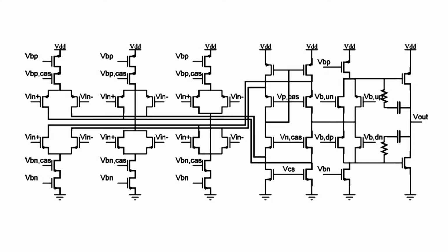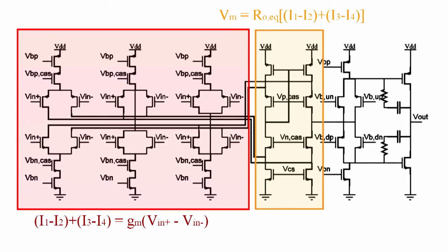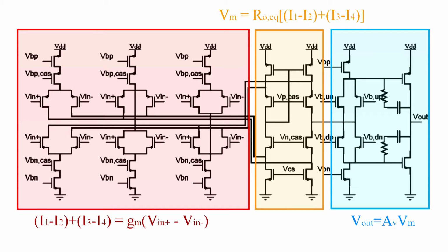This is a schematic of the OTA without bias circuits. It can be broken down into three parts. The first block utilizes a combination of NFETs, which work at high input voltage, and PFETs, which work at low input voltage, to generate constant transconductance against the input common mode voltage. The second block sums up the signal from the first block, which is carried by 4 wires, into one signal that runs on a single wire. The third block is a Class AB power amplifier biased in subthreshold, so that the output voltage can reach the rails without too much gain loss in comparison to the gain in the middle of the rails.